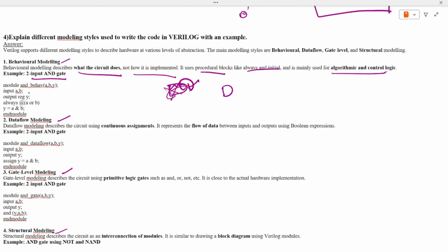You know, right? This AND gate, if you take it, you will have inputs a, b and the output will be something, say Y. Next, you will consider always @(a or b), and next you will take Y equals a and b. Y you will take as a and b. See now how you are taking it: the two-input AND gate, that is two inputs a, b you are taking, and in the output you are giving Y; the same way you are taking AND with a or b.